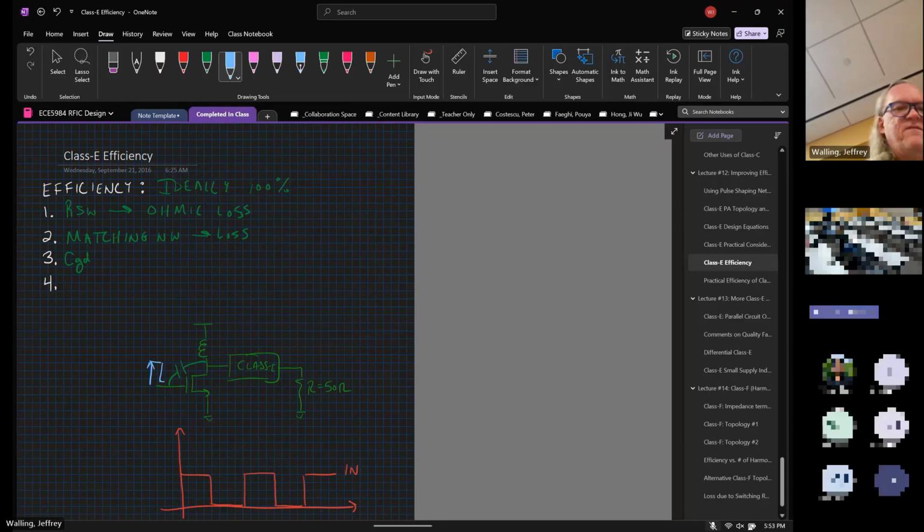So if I have a rising pulse here, I'm going to get a rising pulse immediately at the output. My voltage waveform is not going to be able to go to 0 before I turn the switch on, because I'm going to immediately cause that pulse to feed through. So this causes a feed through from the input to the output. So in order to fix this problem, there's going to be 2 transistors stacked in a cascode.